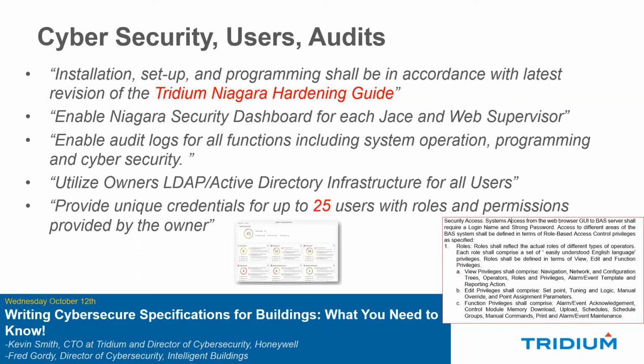The other thing that owners are using today in bigger systems, they don't necessarily want to set up passwords and user credentials in the Niagara framework. They want to link that to their existing Active Directory and LDAP. You take a lot of large school districts, universities, end users, they've already built in accessibility in their own IT system, and they want to piggyback on that. And the Niagara framework has the ability for you to use the credentials that are already built into an LDAP and Active Directory. So that's something that you have to discuss with the owner prior to doing the spec.